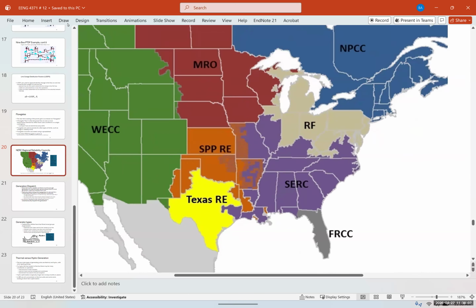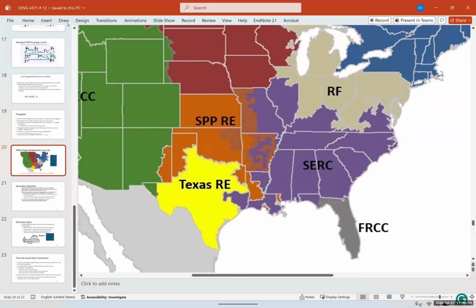As you can see, the ERCOT, or Texas, system is essentially its own island, and it's not connected to others, so they don't have a lot of power sharing. That's the reason we had those blackouts, because it was a very harsh winter. They didn't predict that. They didn't winterize the equipment, and the gas lines froze. The wind turbines weren't winterized either. They froze, so they had to have rolling blackouts, shutting down to protect the grid.